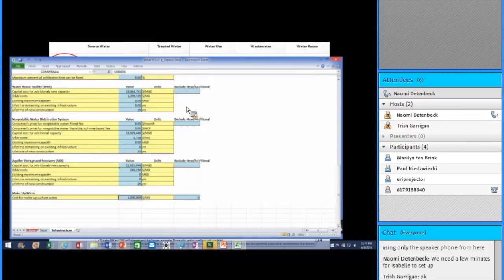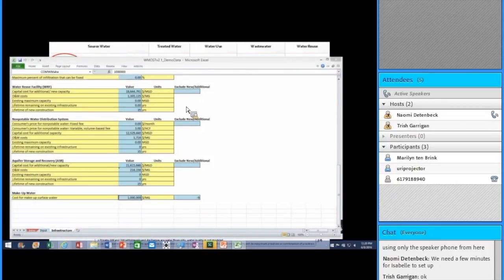And we'll get into that during the discussion of validation and calibration this afternoon, but it's a safety valve for WMOST to use if, during the simulation or the optimization, it finds that it just cannot meet that demand given the options that you've made available to add pumping, or to put additional capacity in your reservoir. It will go fetch that amount of water, make it up, and attribute a very high cost. So it's a last-ditch option that it has available.